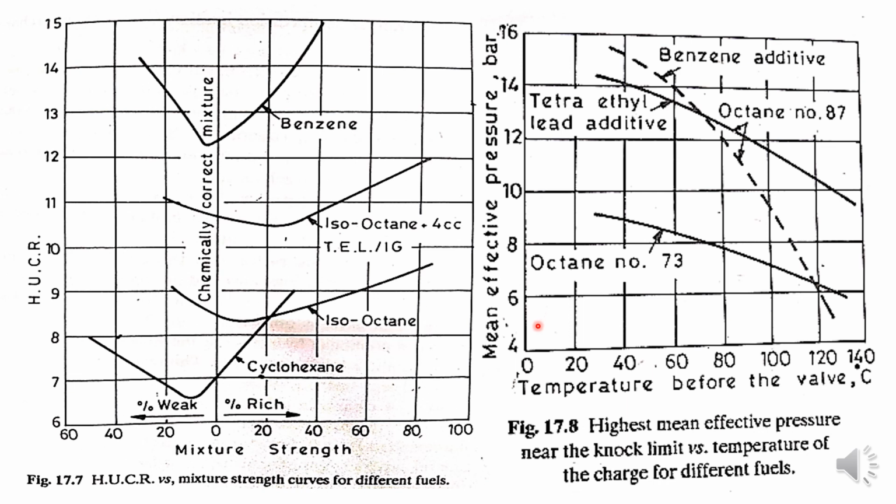And a slight reduction in the lean mixture results in irregular and intermittent engine operation. So usually we won't go for a leaner mixture. Most of the time we will go for the richer mixture. A leaner mixture will lead to intermittent and irregular operation. This can occur with as early as 20% EGR. So the use of rich mixture will result in a high specific fuel consumption for a supercharged engine. Because we are using a richer mixture, high fuel is being utilized, and so the fuel consumption is going to increase to avoid that knocking.